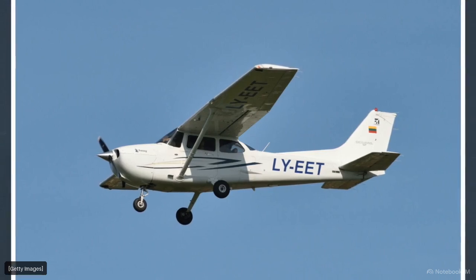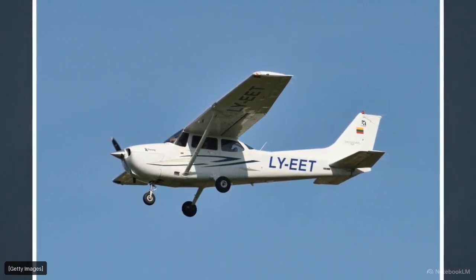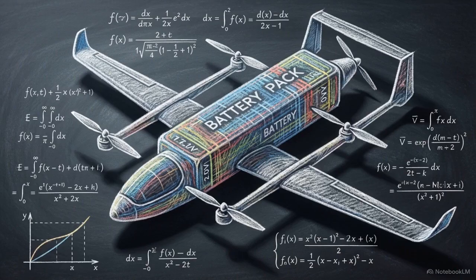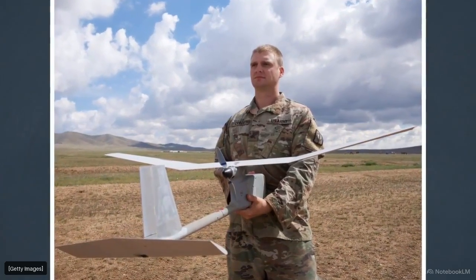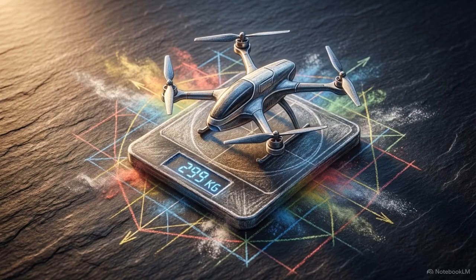Estimating the airframe weight using standard statistical data from manned fuel-burning aircraft artificially inflates the mass estimations for a small electric vehicle. Applying these standard equations mathematically kills a viable design. To solve this, we apply regression models derived exclusively from modern, lightweight composite drones to ensure our empty weight fraction reflects the reality of sub-300 kilogram vehicles.